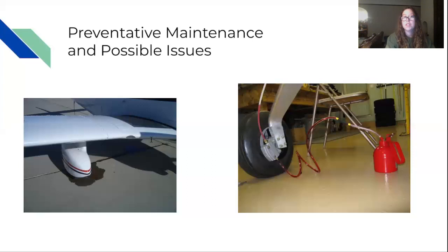And then dirt within the hydraulic fluid and in those lines could cause a lot of problems because hydraulic fluid is also being used as a lubricant throughout the system. So if there's any dirt or anything else, it's going to start acting like an abrasive. And that's why it's really important that if you suspect your hydraulic fluid has been contaminated, to drain it, flush it, and refill it.